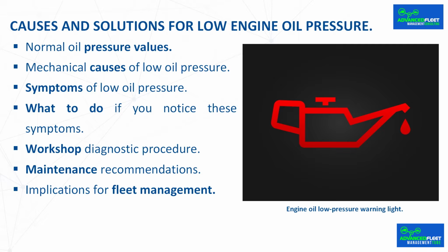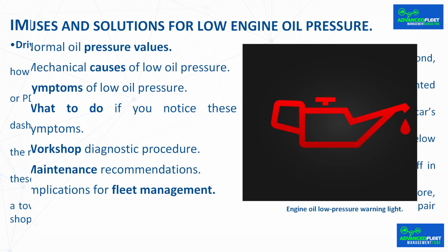Proper maintenance, knowledge of the correct type of oil to use, and periodic pressure checks ensure the engine's reliability and extend its service life. In many cases, low pressure is caused by an oil level below the manufacturer's recommendation, and simply topping off the oil up to the recommended level is sufficient. It is recommended to implement the following measures.